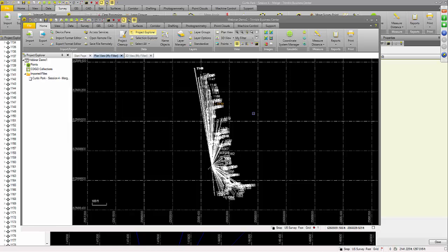Then you can take your KML file that you've created in Google Earth with those lines and points, export those out or save that project, the KML file, and then import it into TBC, and you can compare where your network design was in comparison to where the actual points in reality were.